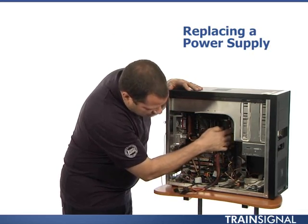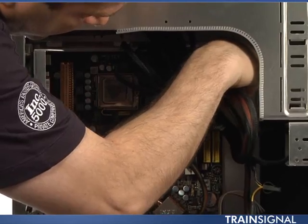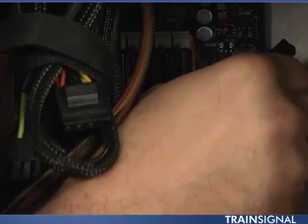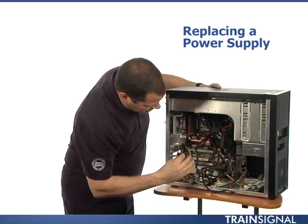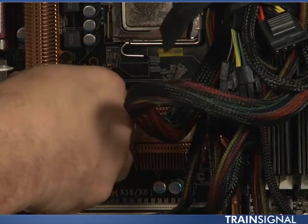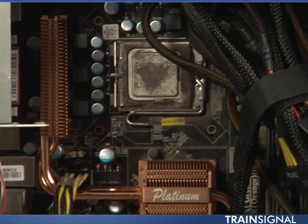The connector for that is right here on the motherboard. So it's a matter of making sure that everything is aligned correctly. Push it in until it clicks. Similar procedure on this side. Next, we have a few other CPU type connectors that we want to make sure are correctly there so that the CPU fans will run as expected. So we have that connected, we have these connected, and we're good to go.